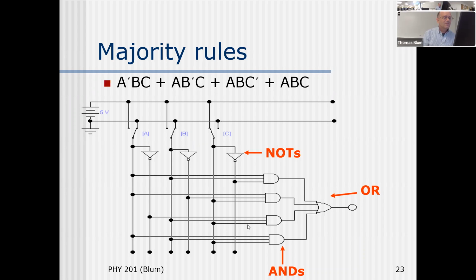Where is the output? The output of the OR gate is the overall output, and I have thrown it into a probe, which is under indicators. The other possibility is to put it to a voltmeter and connect the bottom of the voltmeter to my ground. So this probe is not a real thing, it's just a fake thing for the purposes of the circuit. If it lights up, it's true, it's high, and if it doesn't light up, okay.